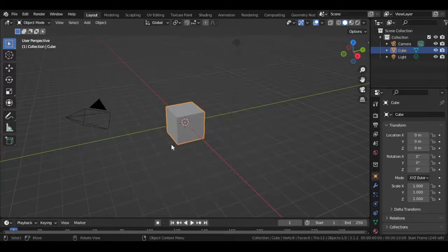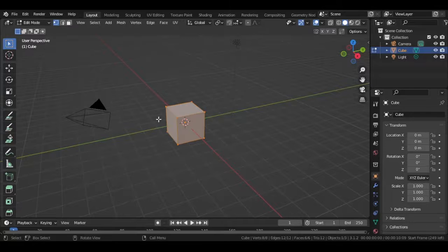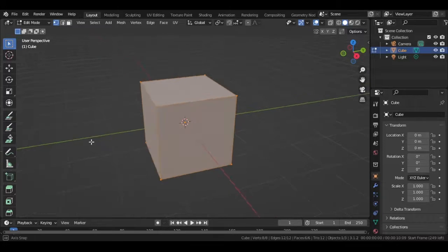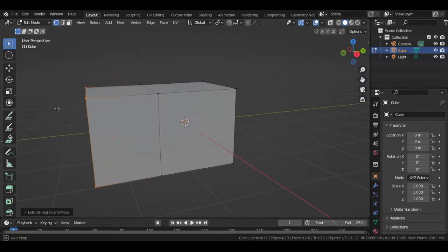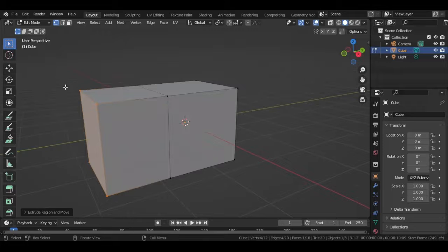You just new general file. You have the basic cube here. You click on it. If it's not selected, press tab. You see the little vertexes pop up. I'm going to make a car. Select these, E to extrude, and move it as far as you want.